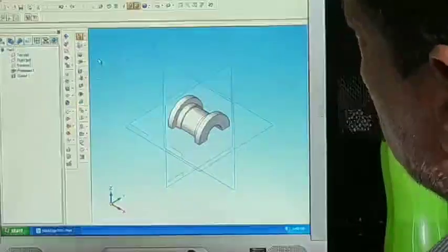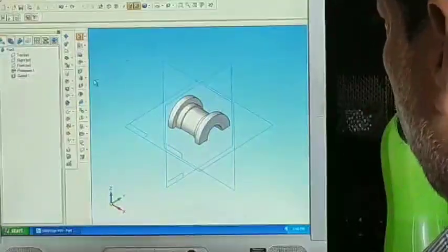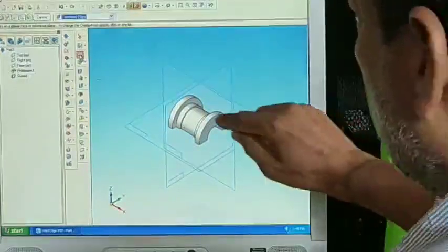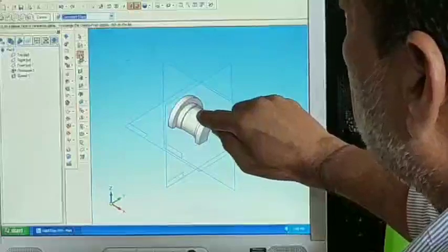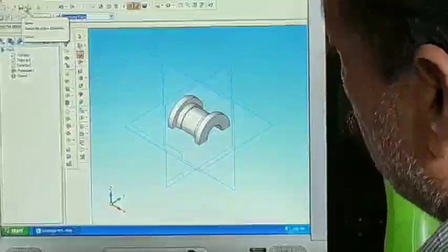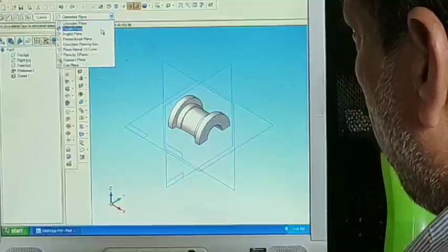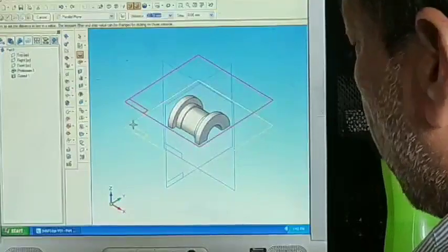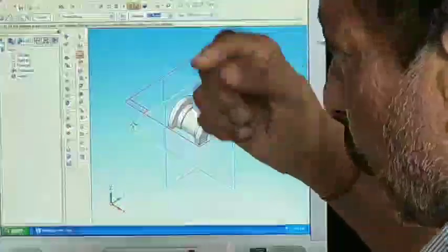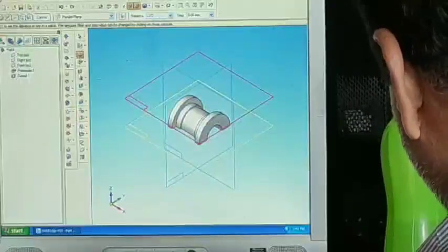So here I am going to construct bearing bottom half. So for constructing bearing bottom half, go to protrusion. So there is a pin, the pin should be inserted or placed here. So for any curved shape, it is impossible to fix the protrusion. So for that one, I am going for parallel plane, parallel to this XY plane. So it should be placed here. This is of radius 17.5, pin height is of 5 mm. So parallel should be of 22.5.